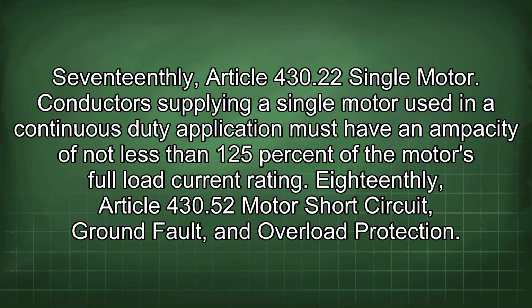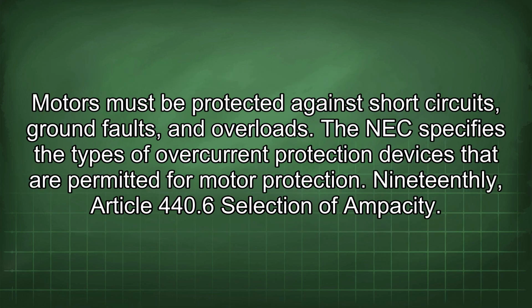Eighteenth, Article 430.52 Motor short circuit, ground fault, and overload protection. Motors must be protected against short circuits, ground faults, and overloads. The NEC specifies the types of overcurrent protection devices that are permitted for motor protection.